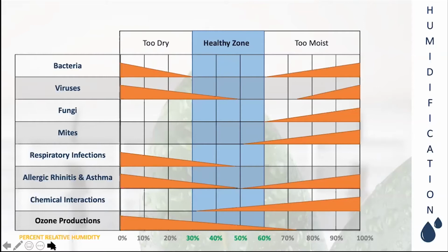Anytime that we introduce high volumes of fresh air, like ASHRAE's recommendation, we're going to negatively impact the level of humidity within the space. And so earlier when I mentioned that we need to take a balanced approach, we have to understand that adding humidification systems to classrooms or office buildings is going to be extremely difficult and not really a practical aspect to fighting airborne bacteria and viruses. And oftentimes being able to manage the level of humidity inside a conditioned space can be done through proper ventilation and through the dehumidification process that is present anytime an air conditioning system happens to be running.